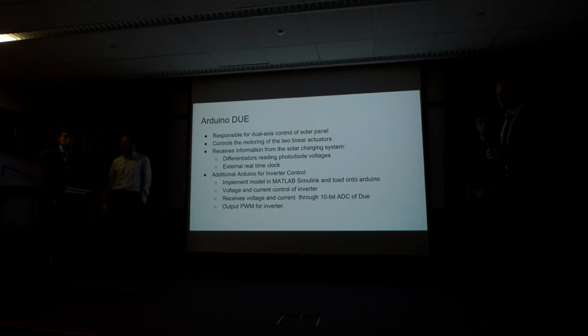During this time, we were able to download MATLAB support packages for Arduino and to test certain situations where we can attempt to apply this to our design. Essentially, we're going to use the 10-bit DAC or 12-bit, depending on the accuracy of our signal. We want to input the current and voltages from the sensors into our DAC, and we want to output PWM signals from our Arduino for the gating pulses for our